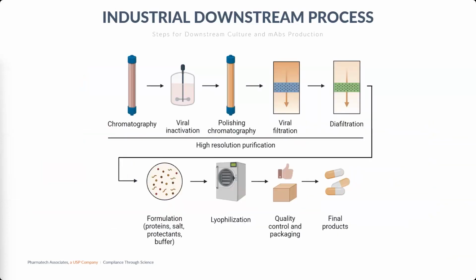Okay, after you've actually made your product, you now have to isolate that raw bulk material and move forward and purify it. This is an effort to remove adventitious materials, whether that be contaminants from the original host cells, which includes other proteins, DNA, cell debris, culture media, co-culture media, and waste streams that have come through that production process.